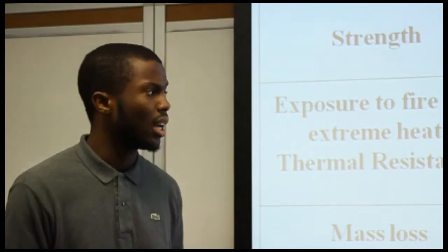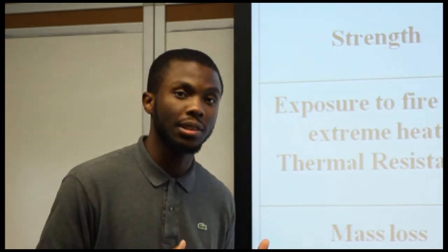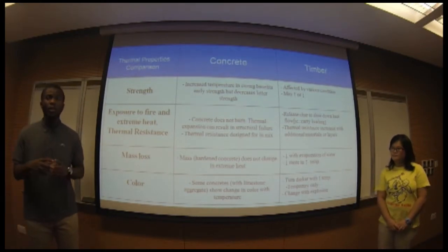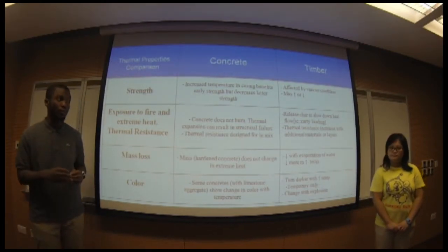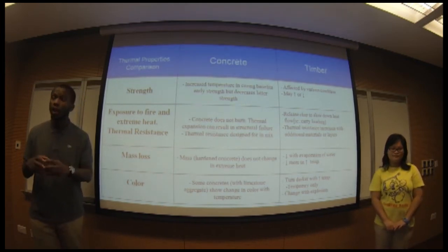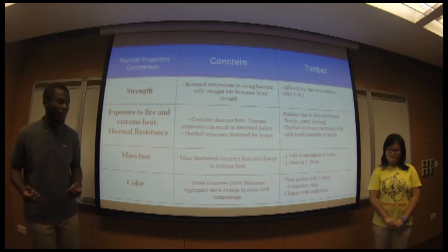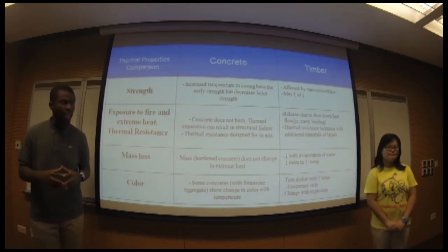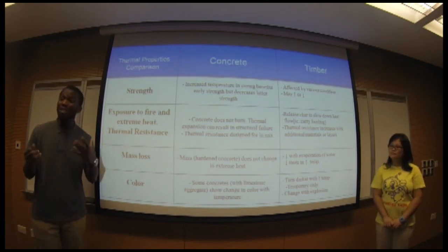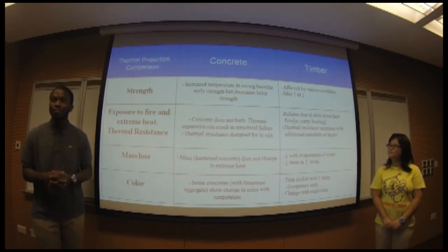Next category will be exposure to fire and extreme heat, as well as thermal resistance between our two materials. In concrete, you must first understand that concrete does not burn. However, thermal expansion can result in structural failure when exposed to extreme temperatures in the case of a fire. And thermal resistance can be designed for in the concrete mix, whether it's with an admixture or how the engineer is designing that concrete mix.